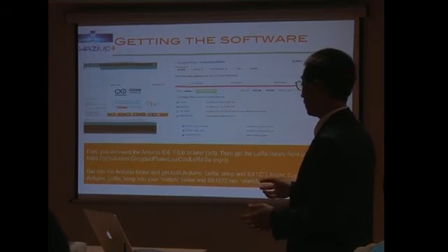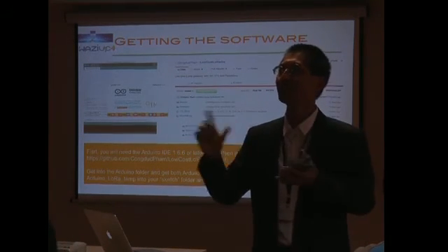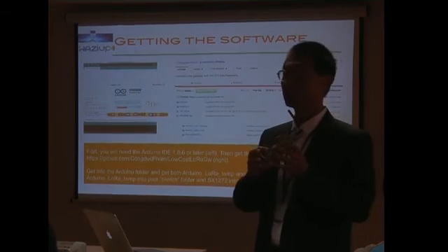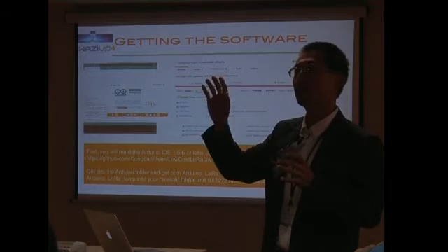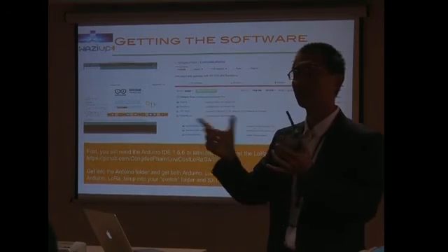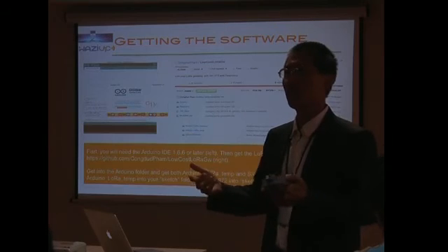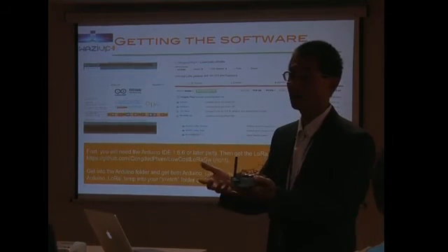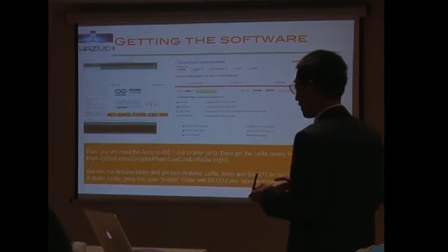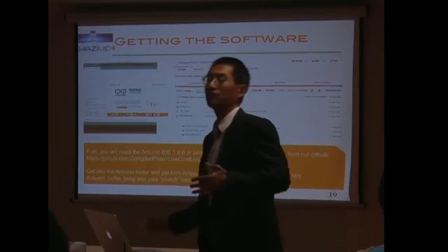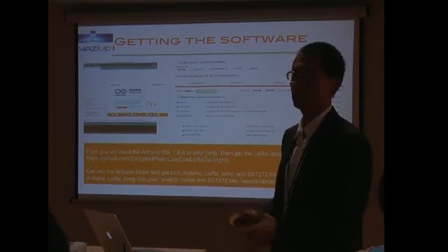Here you have a very simple system: you don't have association and so on. When you want to send something, you just send it, and then the gateway will get it. No association, no SSID, passphrase, and so on, that are related to Wi-Fi access. So, apart from the range advantage, you also have the simplicity advantage of this kind of radio.